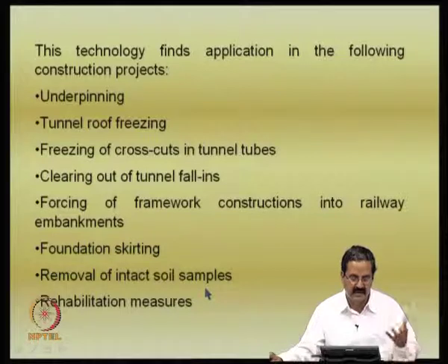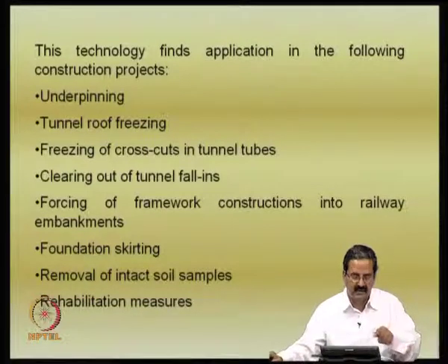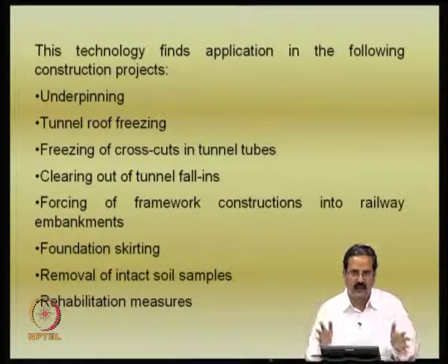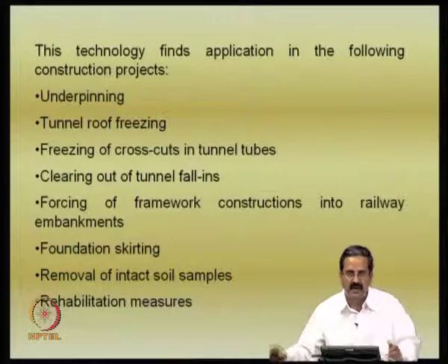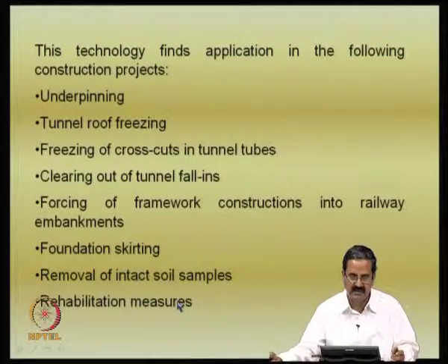Even to remove intact samples, you freeze that area and take the whole lump into the lab and then test that. This is one of the techniques, because you freeze the whole area and take the whole lump, so that way you preserve the in situ structure. It has also been used for a lot of rehabilitation measures.